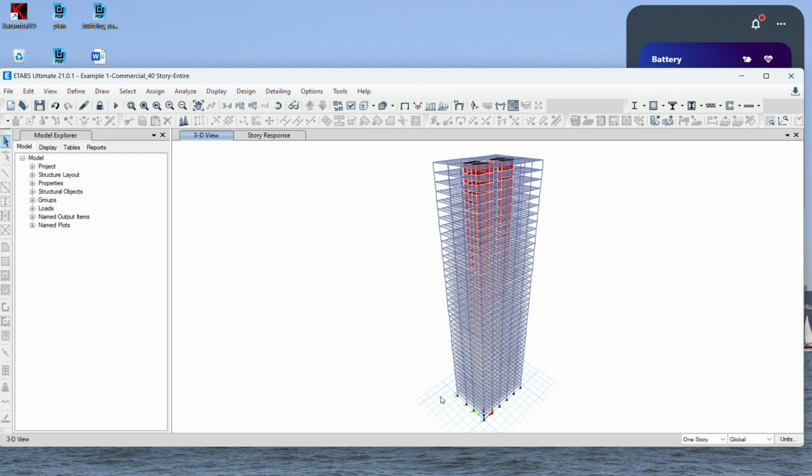define the wall, various wall thicknesses, and also concrete strengths, which means Young's modulus, and also how to assign the elements along this height. We're not going to use the same size all the way up, because obviously that wastes our material. Basically, we're going to make the members bigger at the base and lighter at the top, right? Similar to column design, we try to size the members based upon their demand.